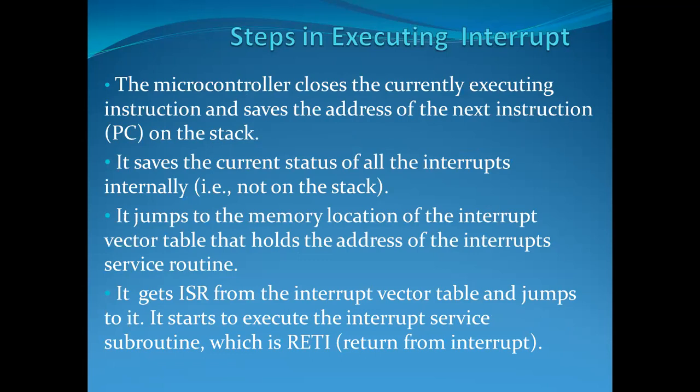Steps in executing the interrupts. The microcontroller finishes the currently executing instruction and saves the address of the next instruction on the stack. It saves the current status of all the interrupts, externally and internally.